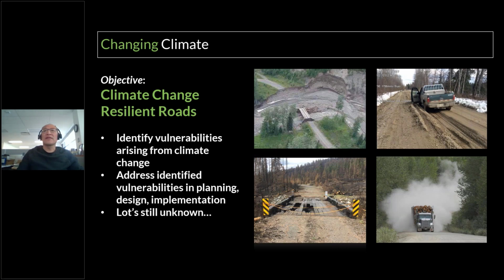So as a result of wildfire, we're seeing not only greater runoff due to lack of interception and retention, but we're also seeing consequences associated with the formation of hydrophobic soils as a consequence of the heat of the fires, which further exacerbates the runoff.